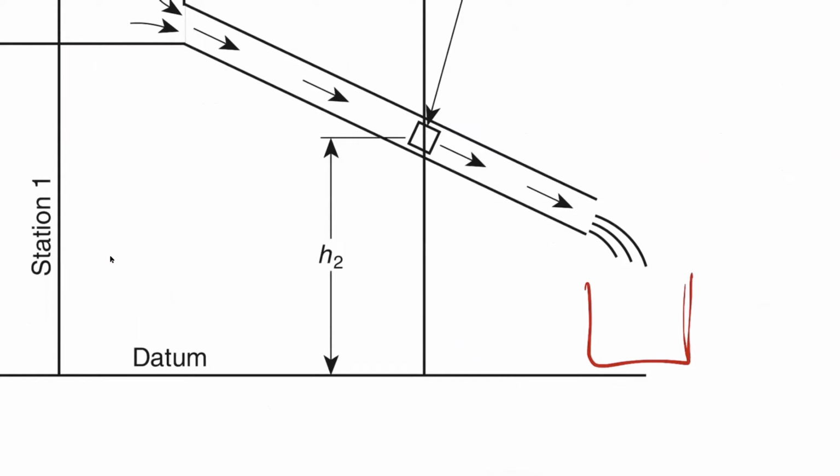The easiest way to calculate it is if you have an empty 1 gallon milk bottle, you cut the top off so that you have more space, and you open the pipe altogether. With a stopwatch or your phone, put the gallon bottle there and see how long it takes to fill up. So you take the volume and you take the time, and volume over time is flow rate.